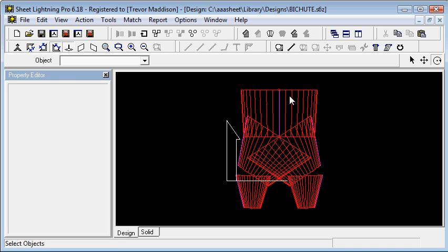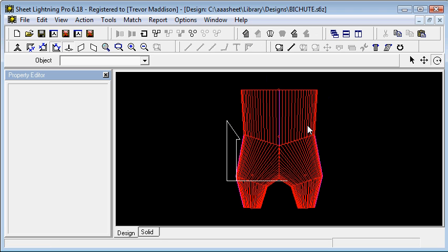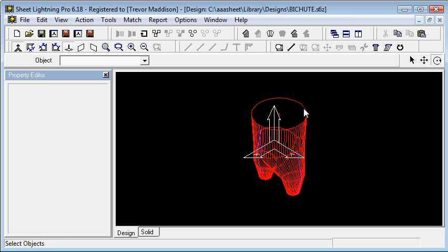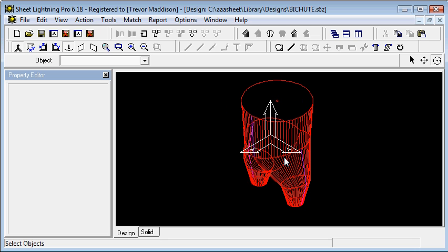Let's just cancel that and unfold that. Weld that up. So we've just welded that design. Let's go back to the 3D view. Now, once I've got a design like this in here, the way to modify it is using these tools rather than parameters, as there are no parameters attached to this. We could actually parameterize it, but the trouble is when designs get complicated, the number of dimensions needed to give it reasonable flexibility just escalates, and it becomes untenable to alter designs that way, and it's better really to use the 3D design system after that.